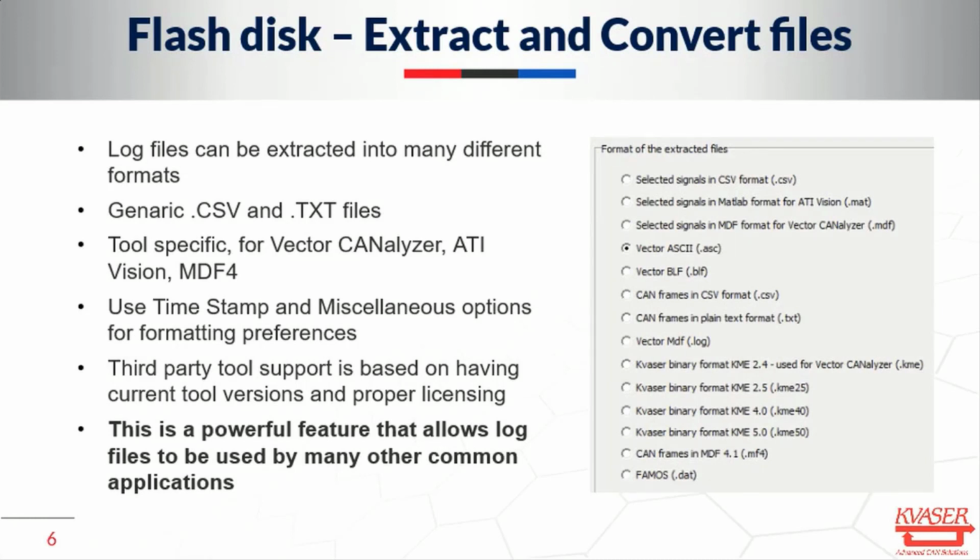So you can format files according to everything on the bus. You can also format according to signals defined in DBC files. So the formatting or extraction option does allow you to use DBC files and extract according to the labels as well. A lot of third-party tools support this extraction scheme. A very powerful feature, it allows log files to be used by many other common applications in the industry.